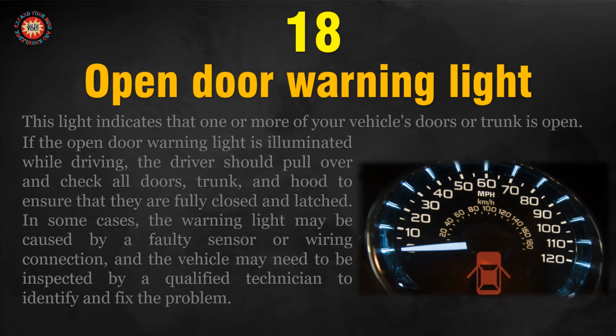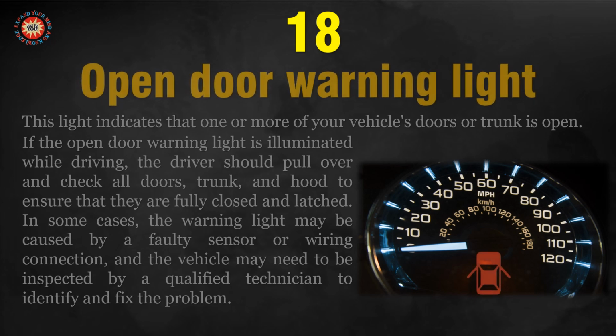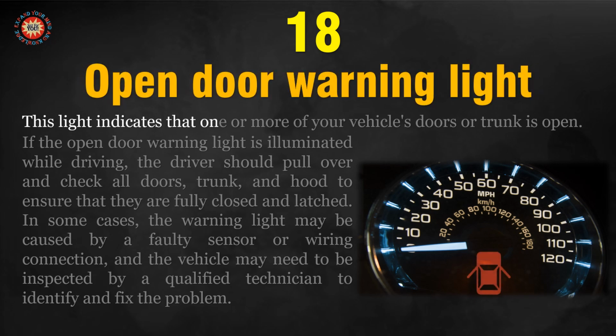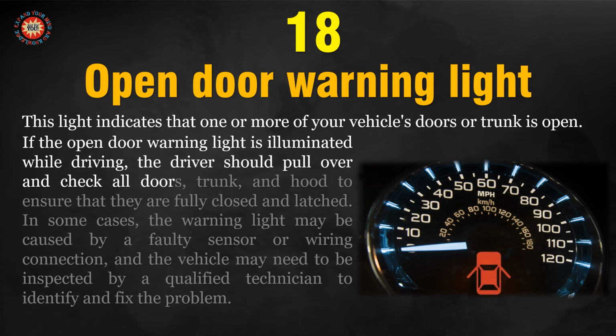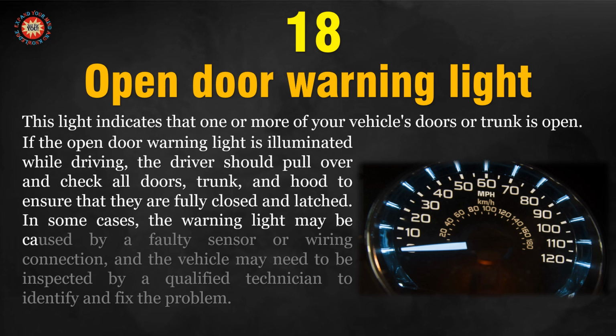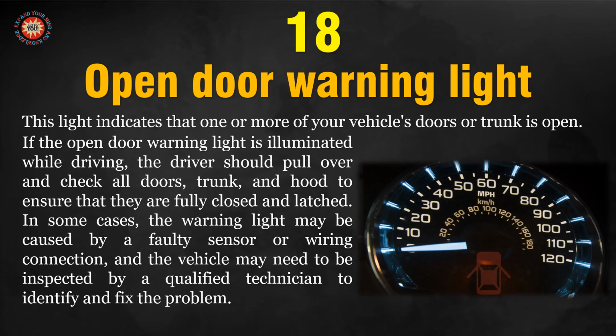Symbol 18. Open door warning light. This light indicates that one or more of your vehicle's doors or trunk is open. If the open door warning light is illuminated while driving, the driver should pull over and check all doors, trunk, and hood to ensure that they are fully closed and latched. In some cases, the warning light may be caused by a faulty sensor or wiring connection, and the vehicle may need to be inspected by a qualified technician to identify and fix the problem.